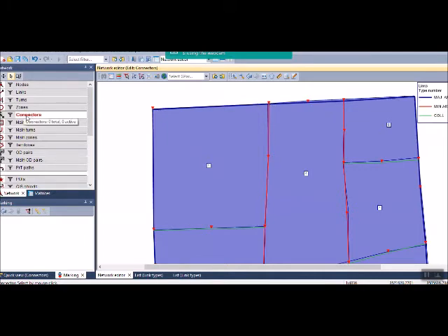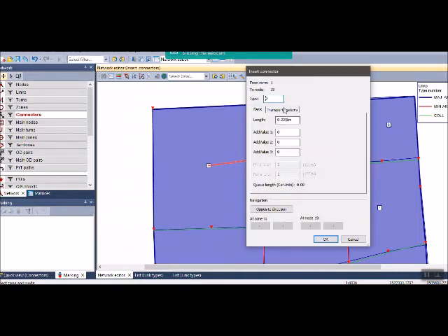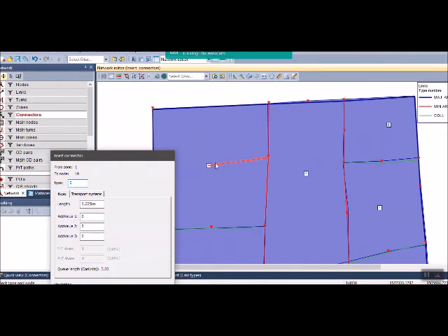So I'm going to select the connectors in here and select the plus and choose from the centroid of the zone to this. Okay, and it is moving from the centroid to the intersection, and this is why I defined a node in here. I defined a node in here because it is not logical to have an intersection between 2 main roads and a local road at the same time.